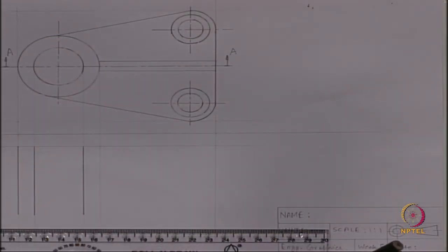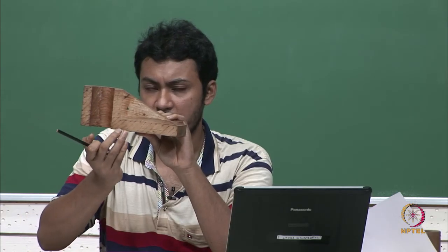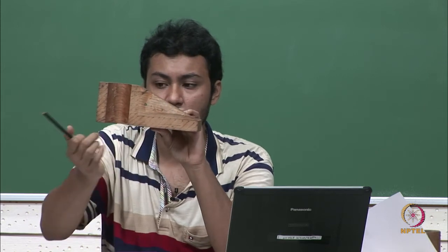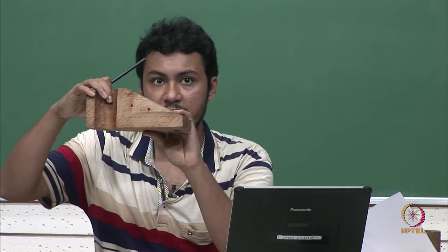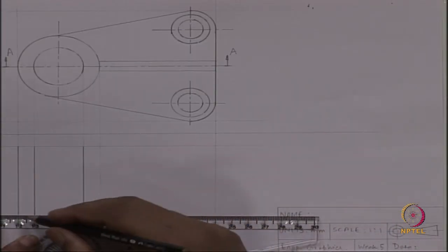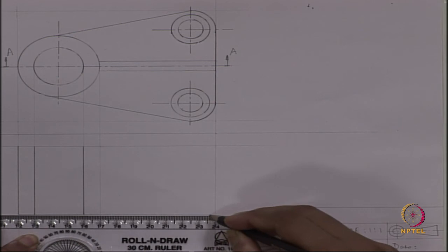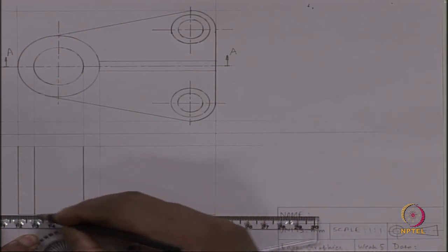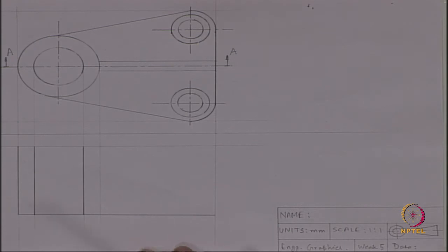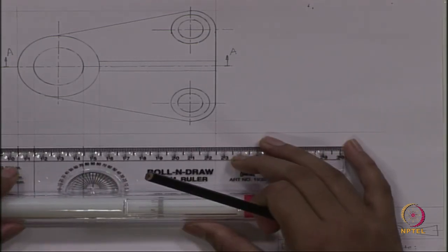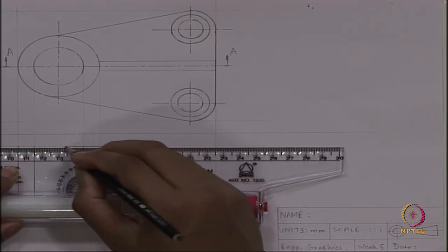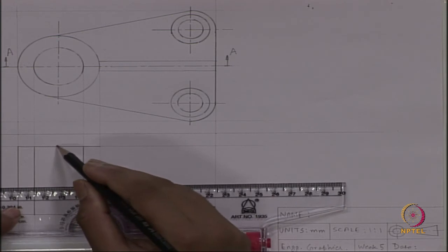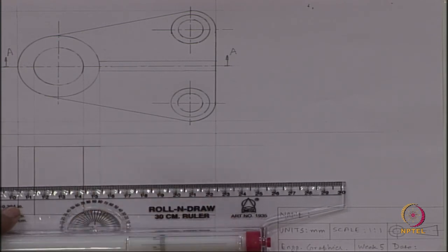And the whole lower part, this line, this curved line and this whole line, if we look from the front, we will look at a single line instead of all these, and that has a length of 120. The top line also we have to join. We won't see any curved line here, instead we will see only a single line. This line was actually curved in the 3D figure, but we will look at a single line only.